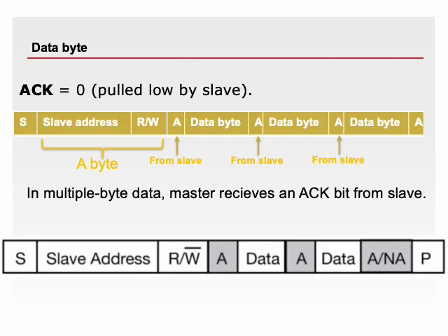We now send data in a byte or 8 bits, starting with the most significant bit. If we have multiple bytes, after each byte, the master should receive an acknowledgement from a slave before exchanging the next byte. This bit is 0 if data has been received. Here the slave confirms its readiness for the next operation. I just recall that the I2C in idle condition is high, and if no response occurs from the slave, the SDA line becomes high, indicating a non-acknowledgement bit or NACK bit.